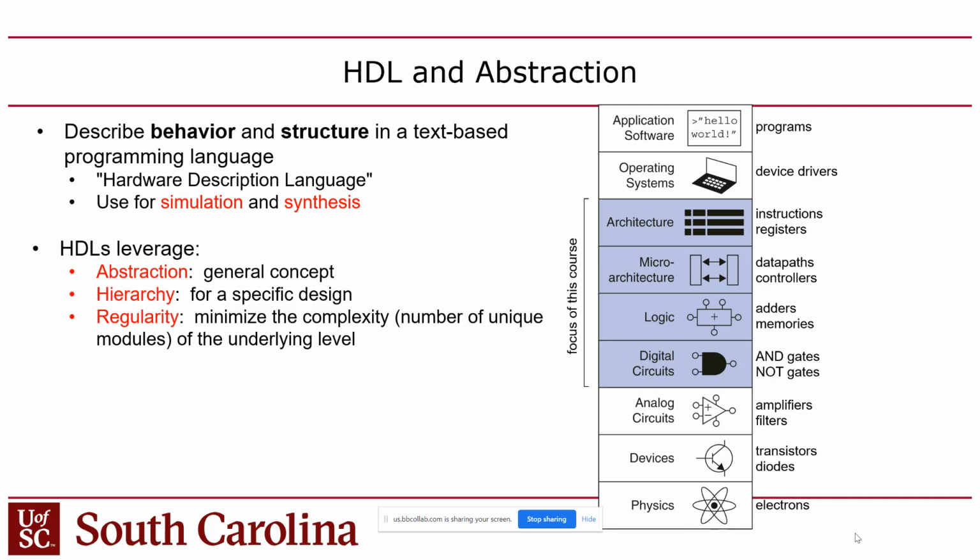I mentioned those terms in the last lecture. So the architecture is basically a kind of black box, like a CPU, it'll run code. If you drill down into that and see how it works internally, it's a microarchitecture, which is digital components connected together, data paths. And then each one of those blocks that make up the microarchitecture is a logic block, and if you drill in there, you eventually get down to where you just have digital logic gates, essentially.